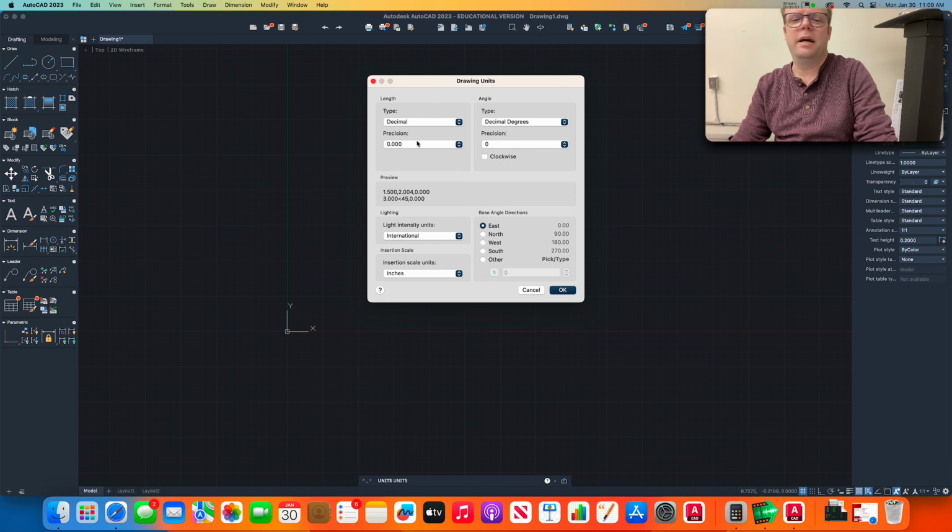And you just need to ask them. When you get a file from somebody else and you want to import that into your drawing, you say, hey, what do your units mean? And they will say, they mean this. And if they say, I don't know, then you say, well, we got to find out because I got to pull this in. And so here are your options. Unitless, which is like, I don't know, that's just AutoCAD units, doesn't matter. Inches, feet, miles, millimeters, centimeters, so on and so forth, nanometers, angstroms, I don't even know what that is. What is an angstrom? Decameters, light years.